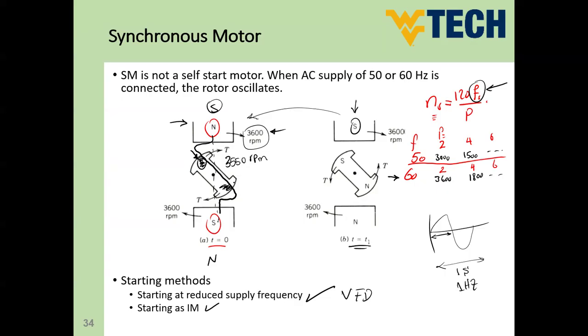And the concept of the piece of iron is, if you have a pole here, the flux line is going to move through the pole, and it will try to reduce its length or its path, so it's going to move this rotor toward the side. So even if you have just a piece of iron, you can do that, okay?